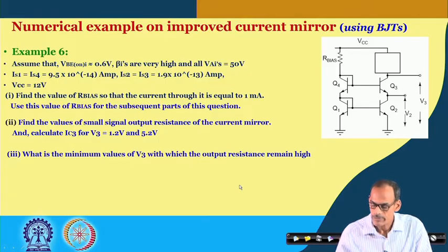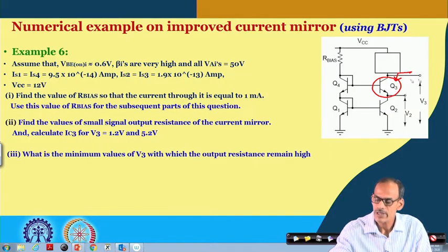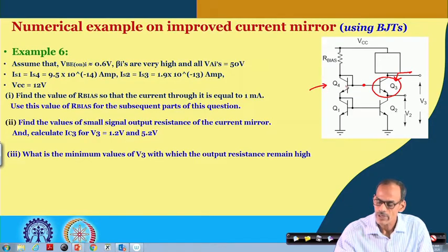So, here as we have done before, we have added transistor Q3 to get higher resistance here and make this current insensitive to the output voltage variation. And instead of giving an independent bias here, similar to the previous circuit example in MOSFET, we have added transistor 4 in diode connected form, so that we can internally generate a suitable voltage here.